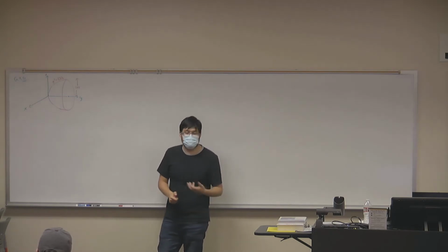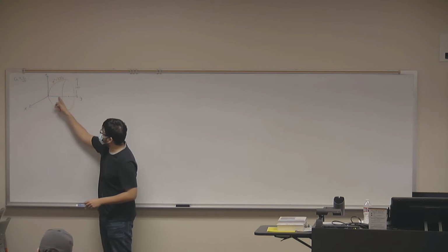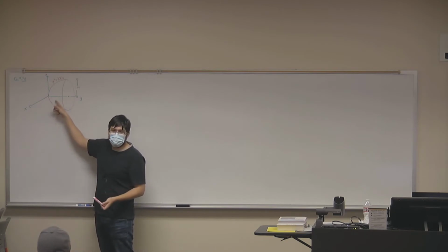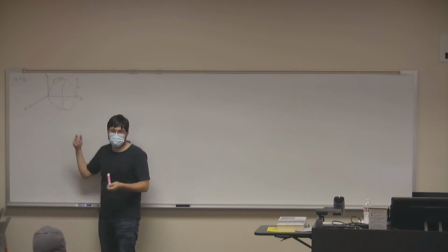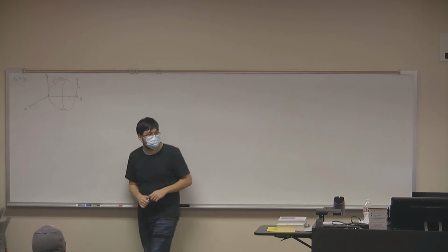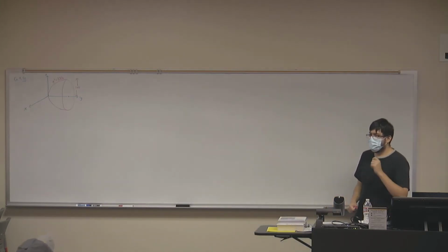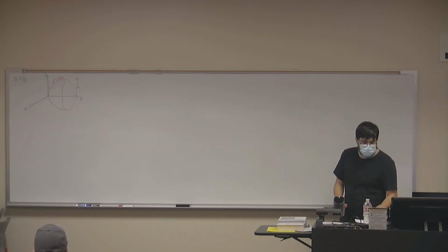So we know that z bar equals 0 because the centroid will be somewhere along this y-axis. In order for a point to be on the y-axis, its x and z coordinates both need to be 0. Otherwise, it wouldn't be on the y-axis. It would be away from the y-axis. Okay? So we expect x bar and z bar to be 0. So let's see if that's actually the case.